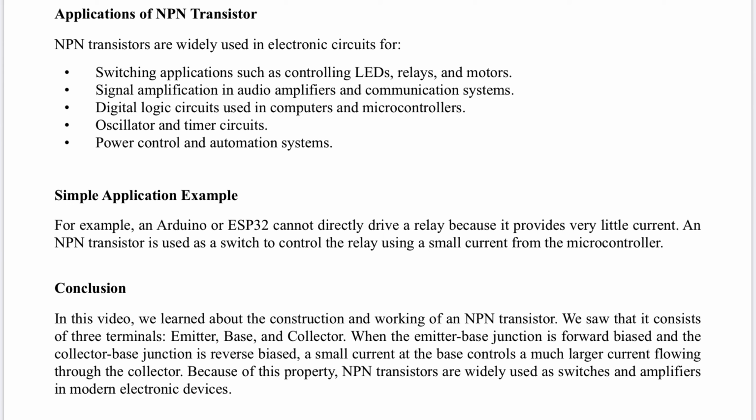Simple application example: an Arduino or ESP32 cannot directly drive a relay because it provides very little current. An NPN transistor is used as a switch to control the relay using a small current from the microcontroller.